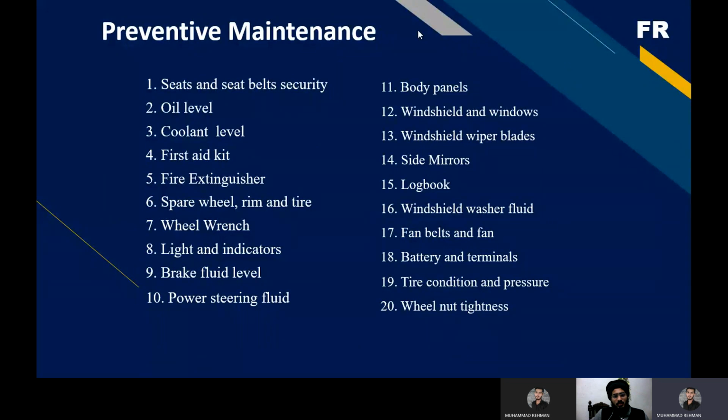And now you also have to see that the brake fluid level is very necessary, because mostly hydraulic brakes are used now, so the fluid level must be monitored, and must be refilled if the level is below. And then comes power steering. Basically mostly hydraulic steerings are used, so you also have to see the steering fluid. And then there are a few other points like the body panel, windshield and windows, side mirrors, logbooks.